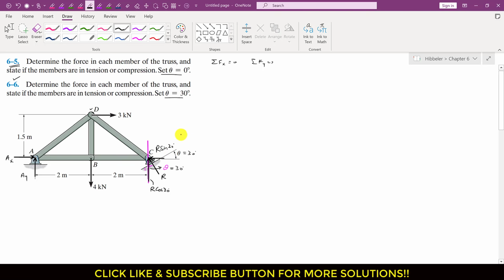sine of 30 degrees. In the first case when theta is equal to 0, R will be acting only in the y direction, that is vertically upward. This is our positive x and y direction. If theta is 0, then this cos component will be R cos of 0, and cos of 0 is 1. So we will have only one reaction acting vertically upward in the y direction. But in this particular case we have R cos of 30 degrees and R sine of 30 degrees.